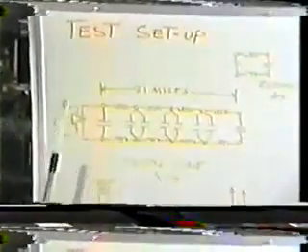What we have, we've taken our element that we've shown and compiled these in series to produce on the workbench effectively 31 miles of transverse electromagnetic transmission line. This might be the power line between the substation and load, or it might be a telephone line connecting two towns together. We have our audio oscillator. We have a stereo power amplifier hooked up for mono, and that is our generator. We've left the end of the line open circuited, so we're dealing with a quarter wavelength similar as before. Now we have a probe for detecting magnetism, and we have a probe for detecting dielectricity.